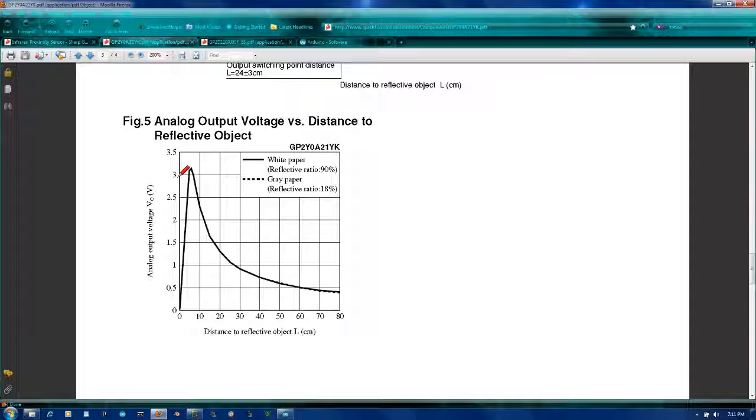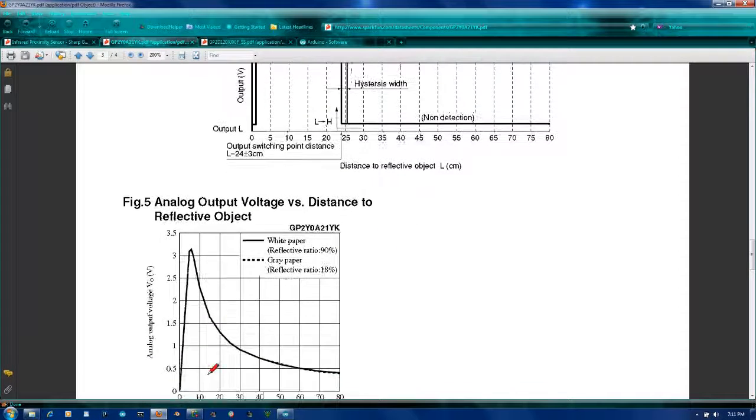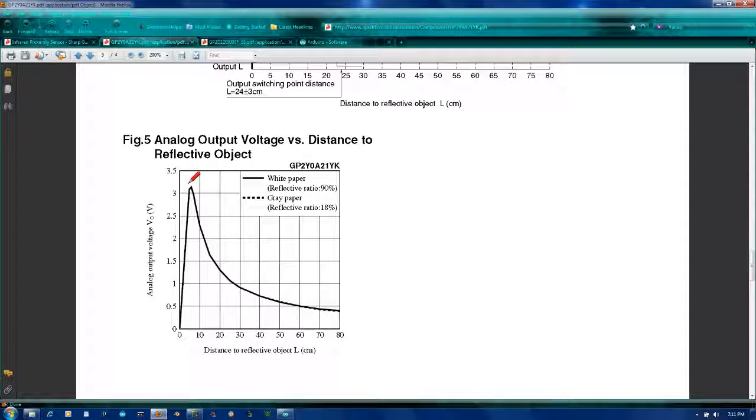Or actually how you determine the voltage and the numbers you're getting back from the analog pin on the Arduino. We could actually map it back to the voltage right within our program if we wanted to. But anyways, enough said. I just wanted to mention that because it wasn't an even distance between all the colors, and that was because this is not a linear line in the graph. It's actually this curved line here.